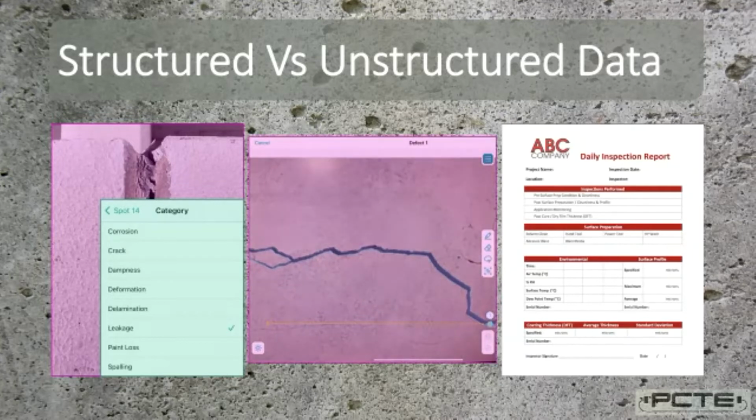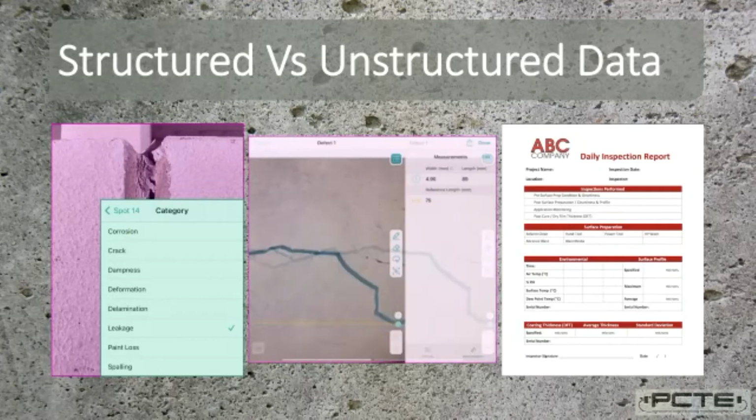With our defect map, we know that we've got a representation of a crack map, but we don't know how wide and how long. So we add the width measured optically, the length calculated, and some reference information about how big the picture is. And there we are. We've got a meaningful point of structured data that we can actually process. Look for all crack widths above 0.1 millimeter, for example. So if we don't have this stored, the picture doesn't have meaning to a sorting, processing, filtering, searching function.